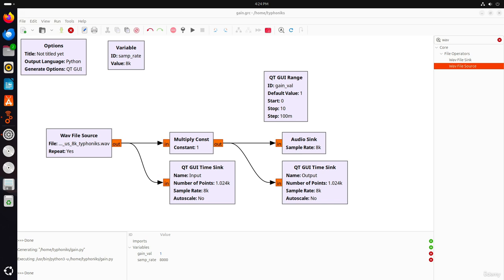If the cutoff frequency is set at 2 kHz, frequencies below 2 kHz pass through and frequencies above 2 kHz are blocked. Real-world filters, however, are not perfect. There's often a transition band where frequencies near the cutoff are partially attenuated instead of being sharply stopped.